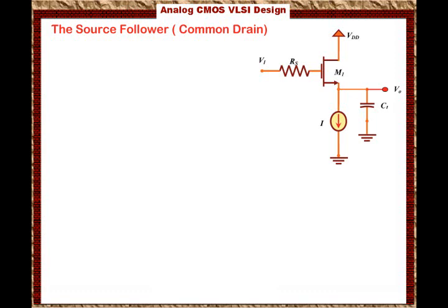So for now, we will say that CL is a dominant large capacitance because this particular amplifier is usually used at the output stage, which means that this amplifier usually is connected to the output I/O pin of the IC chip. So sometimes you have to take this output into an I/O block because you have electrostatic discharge and so forth to protect the chip from damage.